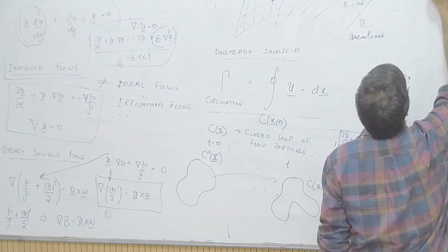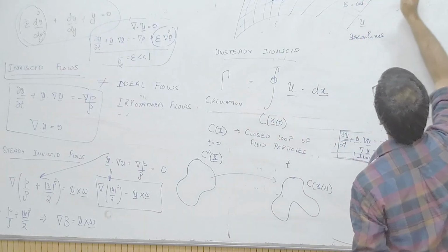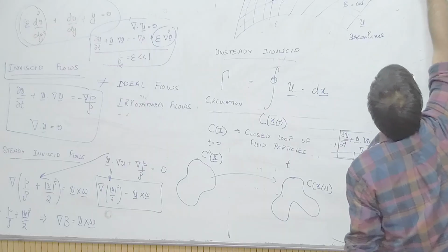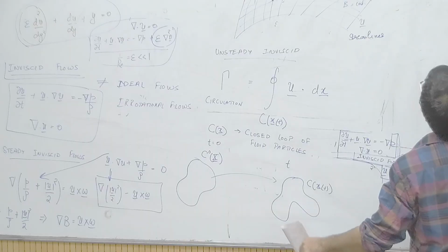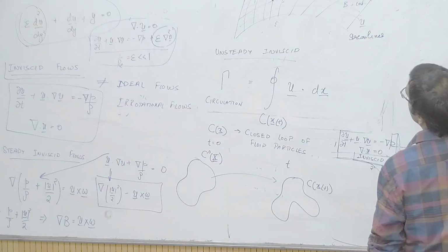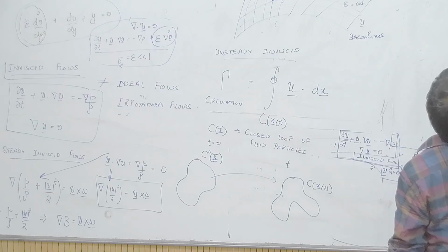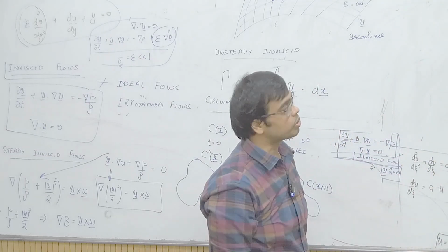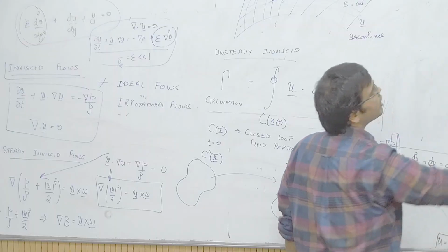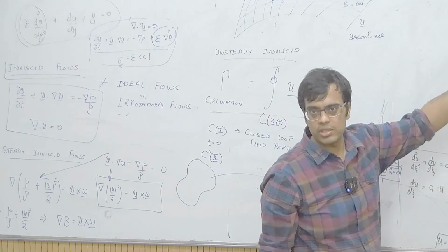So d gamma over dt. This becomes the material derivative because gamma is going to be a function of time; actually it doesn't matter if you specify it as a material derivative here or not. We are going to apply the same transformation that we did when we derived the Reynolds transport theorem. I cannot take this derivative inside because my integration limits are functions of time as well.